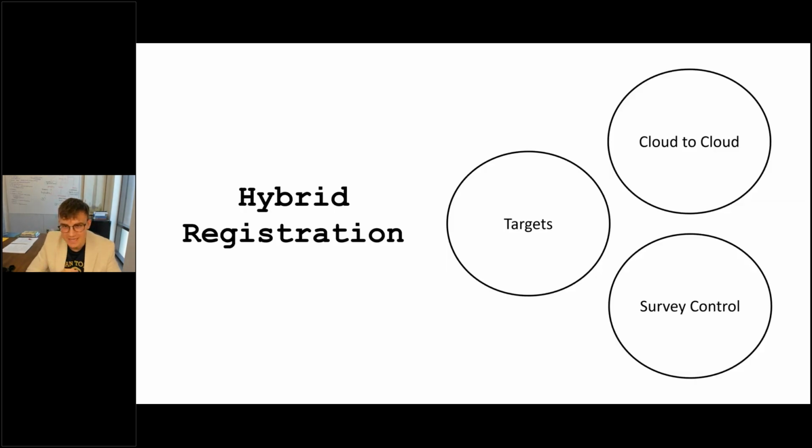All techniques have strengths and weaknesses. The best option is to mix all of them together. Most registration constraints will be cloud to cloud, since generally cloud to cloud is really accurate. But does that mean you should only rely on cloud to cloud? No, because of the challenges we've discussed, but also because targeted registration is a lot easier to troubleshoot when things go wrong. So target errors are just easier to understand.